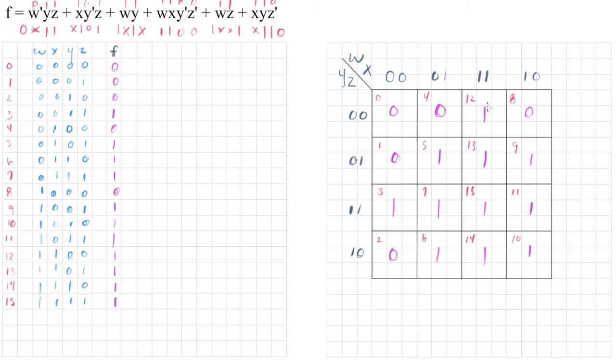And we're limited. So we're going to have to take this row here, or this column, take this entire row, and then we're going to take 4 squares I can see. So 1 here, 2 here, 3 here, 4 here. So our minimum expression is actually going to have 6 parts to it. So we're not minimizing it, but we're likely going to get rid of a lot of NOT gates. So I'm going to do this by color here.